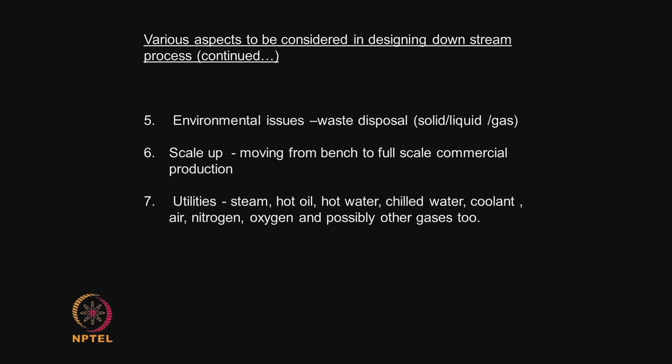One is that the cost of the solvent could be very high, and number 2 is that I will be generating a lot of waste solvent which cannot be thrown out like that. If I am using 2 different solvents, then I am in big trouble, because I will be mixing those solvents and then recovering each of the solvents independently is going to be very difficult. So, try to use fewer solvents instead of mixing solvents. Gas. Can I just vent the gas out?